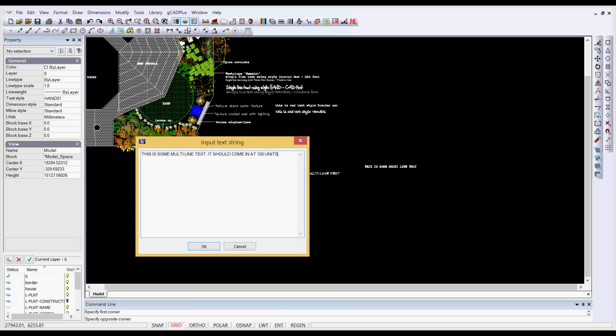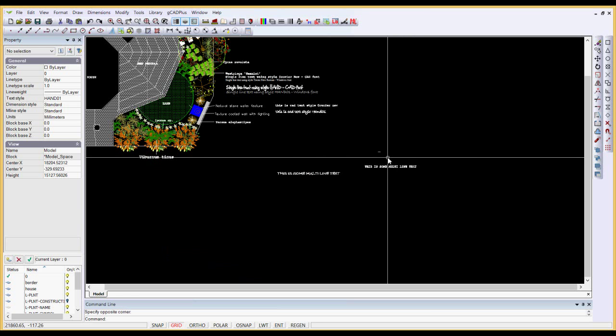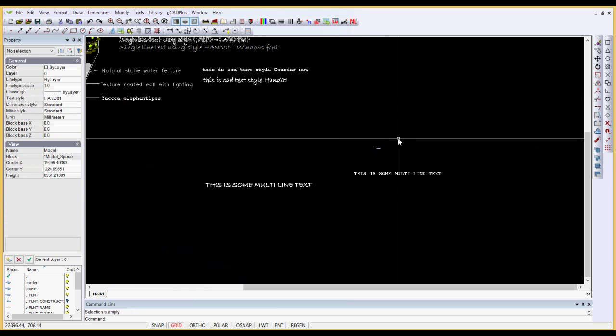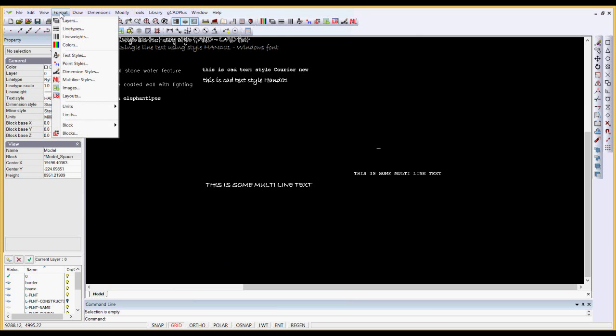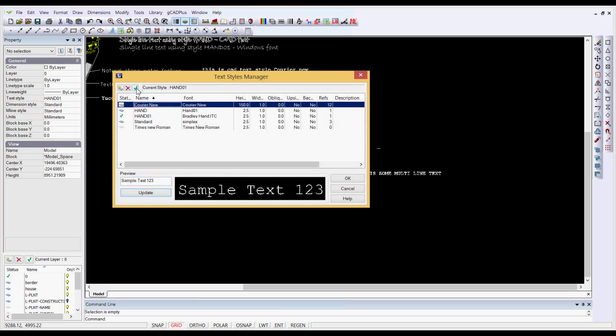I'm working in the metric area here, but you might want to set that as something like 0.8 of a foot if you're using in the imperial area. Now you'll notice that that did not work for us. And I think the reason it did not work for us is that we had not set Courier as our current style. That was the one we'd adjusted.